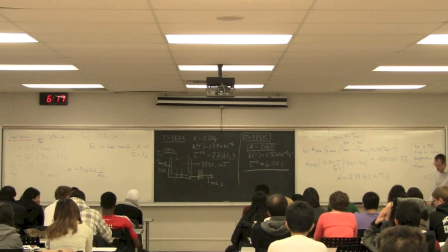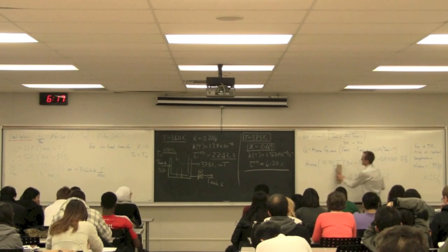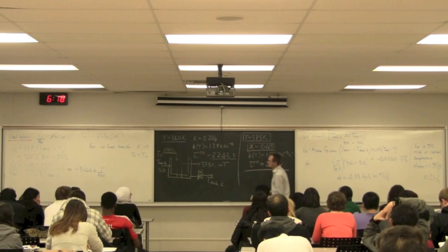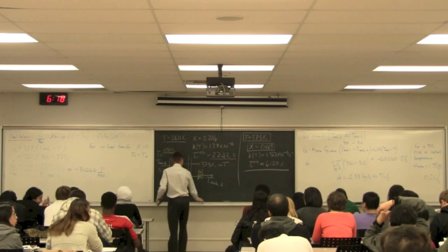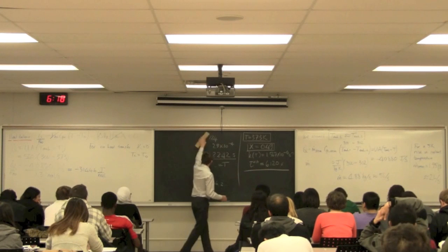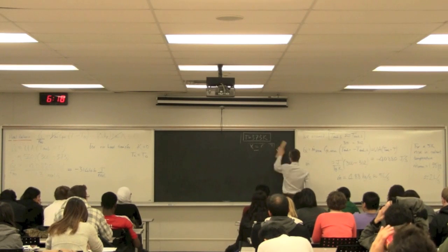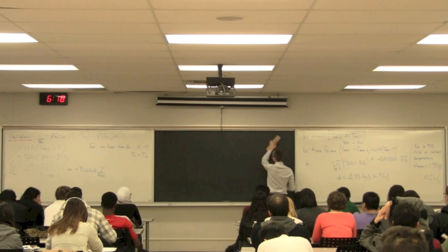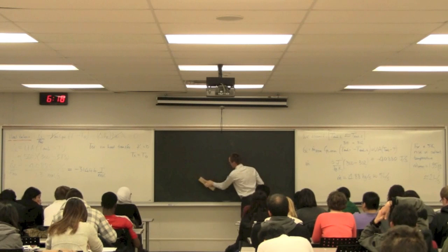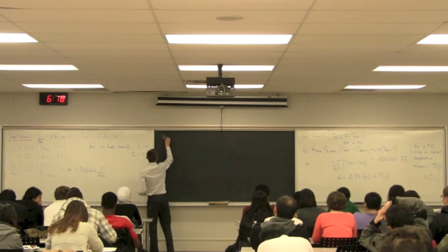One easy way to check that you've got your sign convention correct is, let's take that first equation over there, this heat balance that we started this evening off with, and set conversion equal to 0. So assuming I'm just feeding in my reactants, and for example, I've maybe not added my catalyst, or I'm not starting my reaction in some way, so I'm getting no conversion.